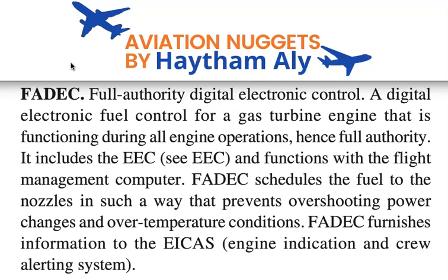If we start the engine automatically, the FADEC will monitor the EGT, exhaust gas temperature, and the N1 and N2 speed, RPM of the engine, and protect the engine against overspeed and over temperature. Maybe the FADEC will abort the starting sequence if a high EGT or a high RPM happens.